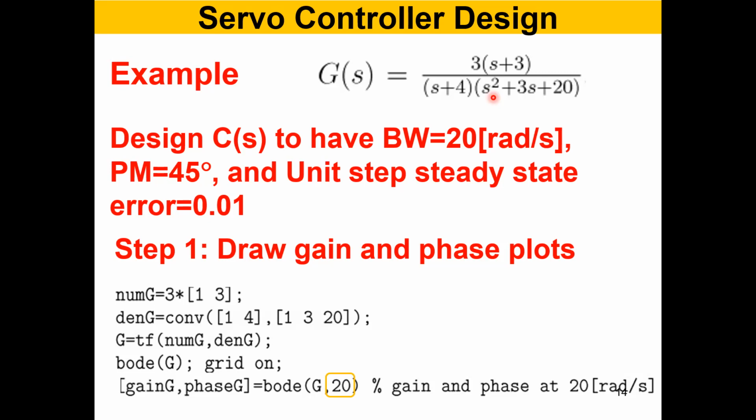Okay, so you can safely say that is the bandwidth. Sometimes when you define bandwidth in filters, you know it is defined at 3 dB cutoff, half power. So that is one way of defining the bandwidth. But here in control systems, you can reasonably take it as 0 dB or unity bandwidth. Okay, right.